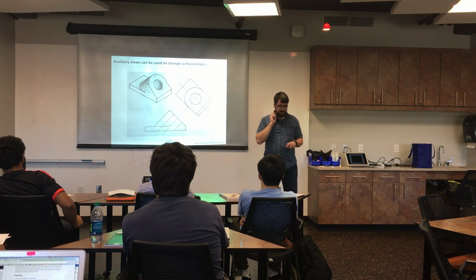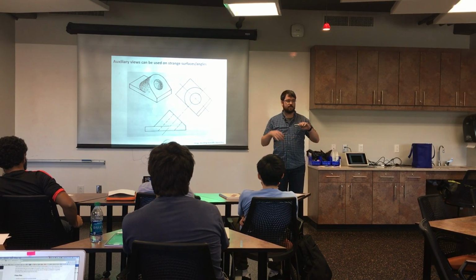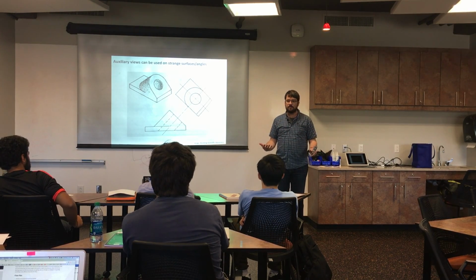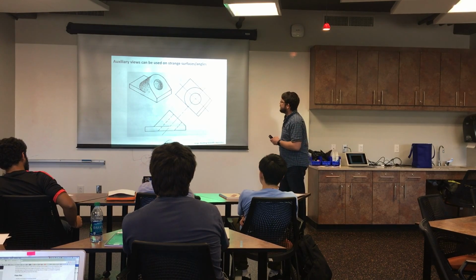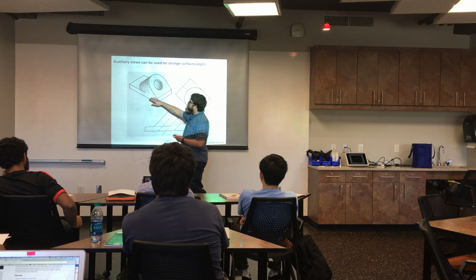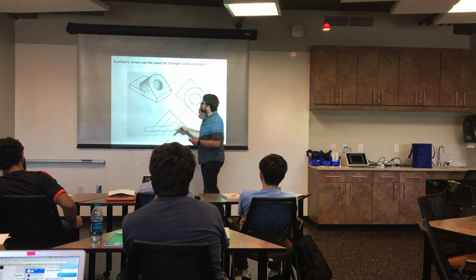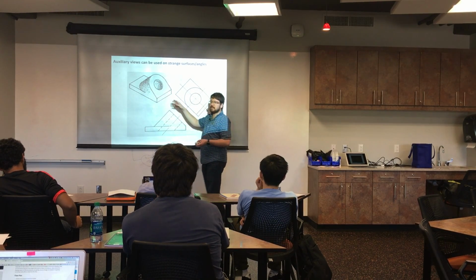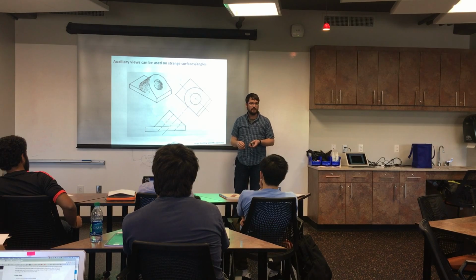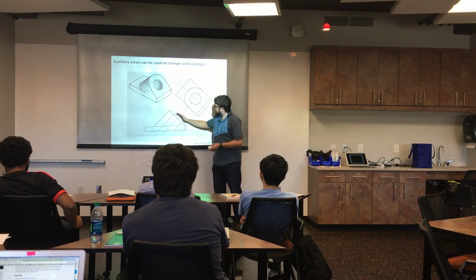In some cases, you'll want to project the part on a plane that is not top, front, back, right, left, bottom. You'll want to do a weird projection. Those are called auxiliary plane projections. Say we've got this part where we have a hole for some kind of dowel or shaft that's going to come down at an angle. Well, in the top view, this is going to look like an oval. And maybe that's not the most useful thing to show our machinist and specify it's a round hole. It's true, but we can make an auxiliary plane view.